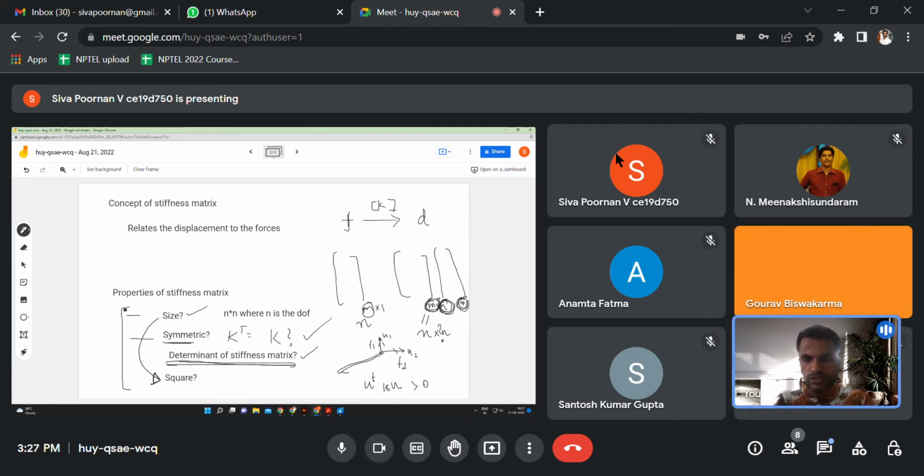Anyway, that is one point, and another point is, as you asked, we are imposing the displacements on the displacement vector. Yes. So you are right. It won't affect the stiffness matrix unless we reduce it considering the boundary conditions. When we say the determinant of the stiffness matrix after applying boundary conditions, we are actually meaning the reduced matrix, not the initial matrix of the full size. That, as you said, will remain unaffected even after changing the U vector. We have to change the whole entire